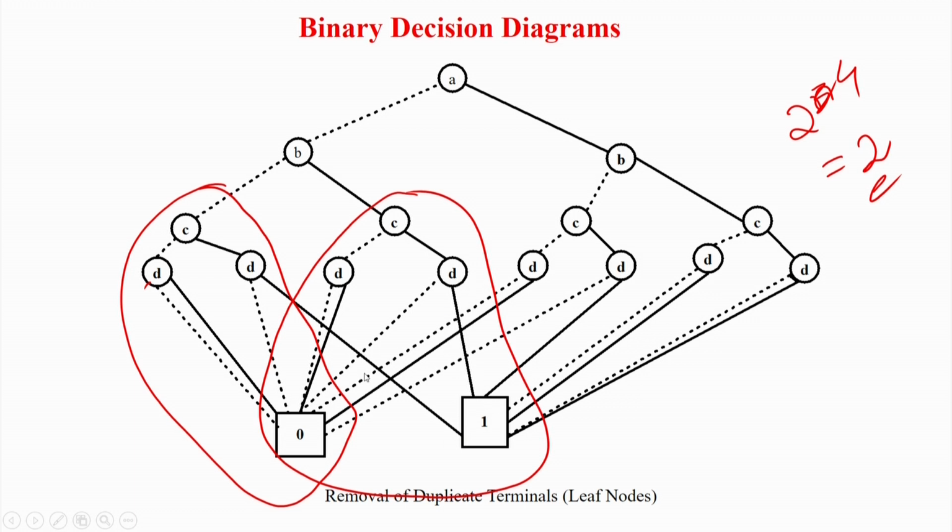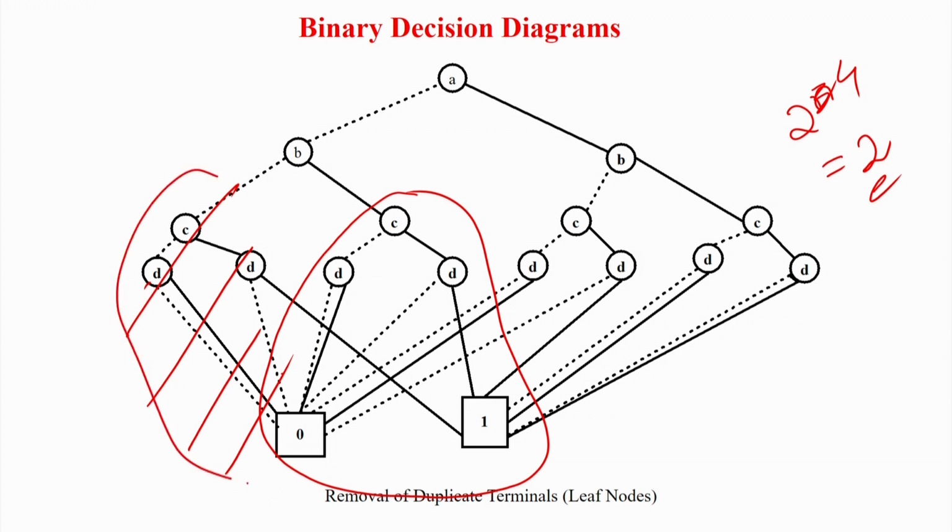So these are the two, there may be more. There are similar other subgraphs which are common. These two subgraphs, or sub BDDs, are redundant, because they are exactly common. So basically one of them can be easily eliminated. This part can be eliminated. Of course the leaf nodes you have to keep. So this part can be very easily dropped out, because they are very similar. You just keep one of them and readjust accordingly. That means if you eliminate this, B only has to be redirected over here. Your job is basically done.